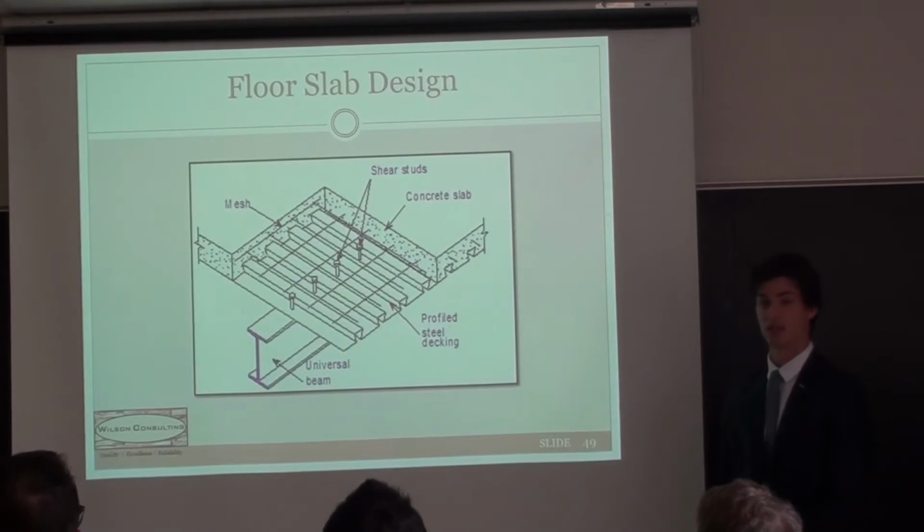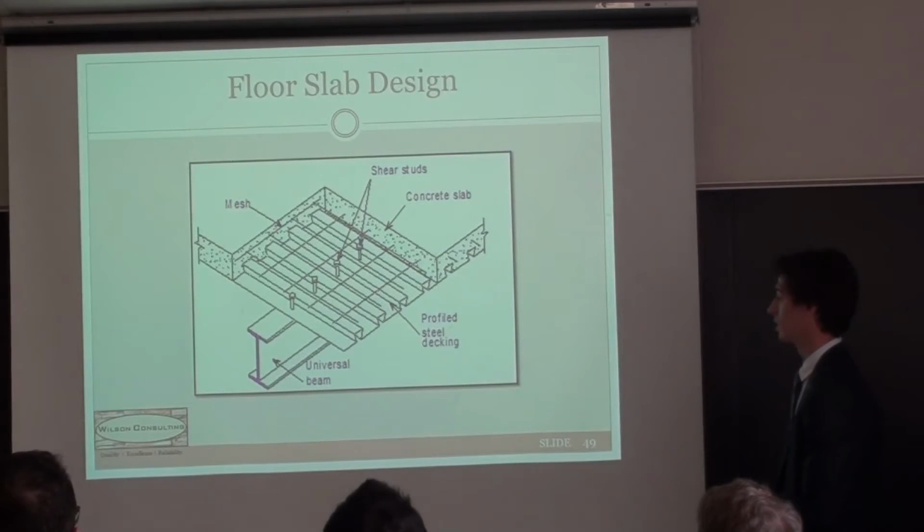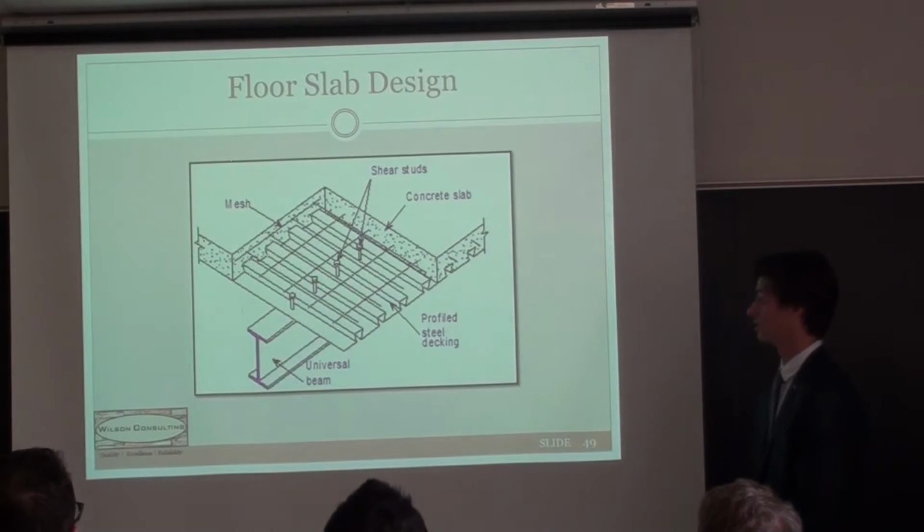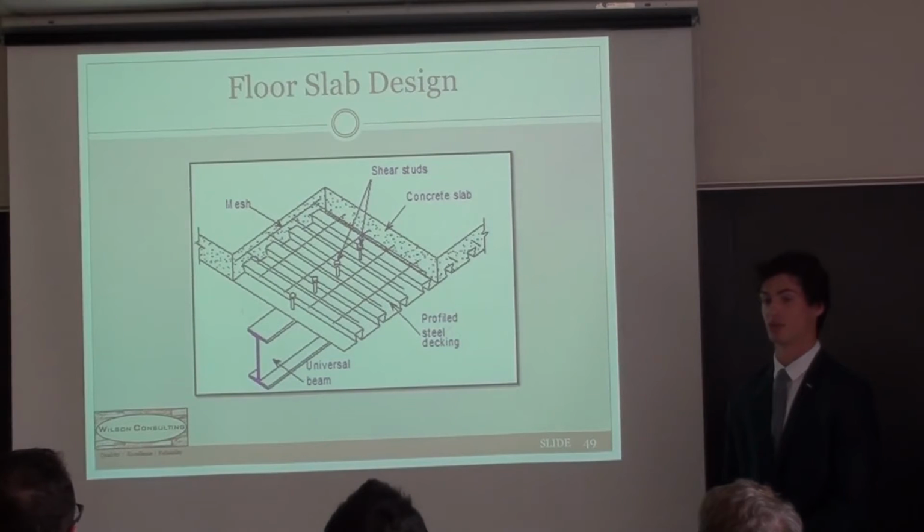Here's our floor slab design. We will be using steel decking with a 4-inch lightweight concrete slab on deck, and we have shear studs to help transfer the load into the beams. And we went with steel decking over straight concrete for sustainability and increased strength.